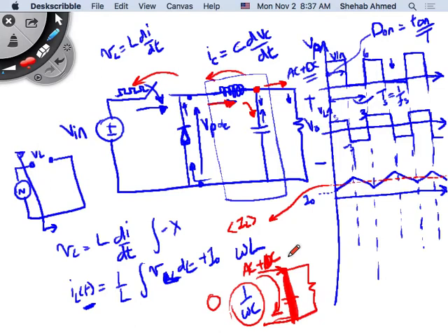If the capacitor is small, then there's a finite amount of AC component that's flowing into the capacitor, and the rest has to flow through the resistor, right? But if the capacitor is very, very large, then all the AC component will flow through the capacitor, and the DC component will flow through my resistor, go to my load. That's the ideal case.